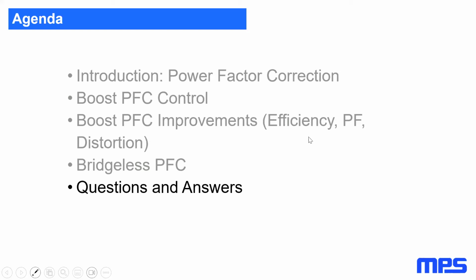If you want high efficiency, very high power density with minimum hotspot on your board and so on, then probably the totem pole PFC will be recommended. If you have plenty of room, not so many constraints, and you're targeting a low cost application, then probably not. So it really depends on what you're trying to achieve and what your budget is.